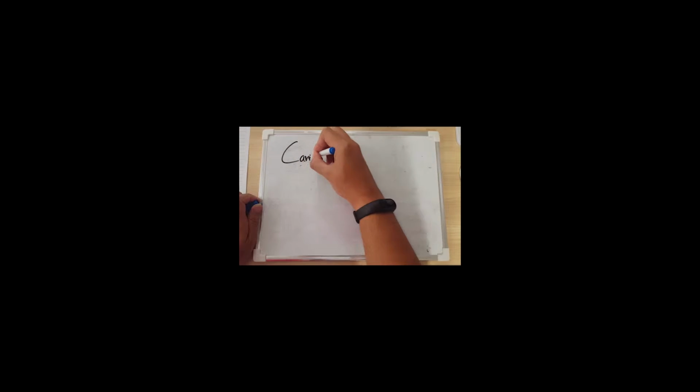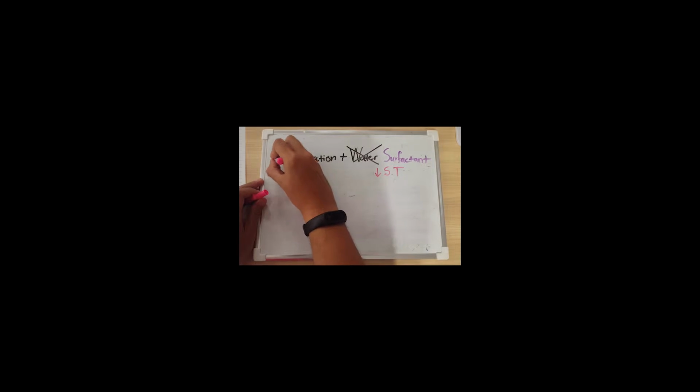Ultrasonic activity, which we can refer to as cavitation, helps the solution to do its job. Plain water would not normally be effective. The cleaning solution contains ingredients designed to make ultrasonic cleaning more effective. For example, reduction of surface tension increases cavitation levels, so the solution contains a good wetting agent or surfactant. The correct composition of the solution is very dependent upon the item cleaned.